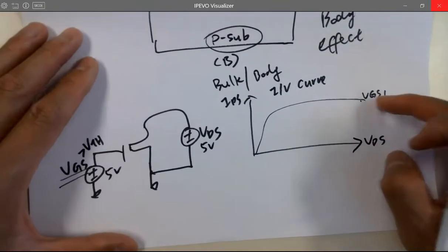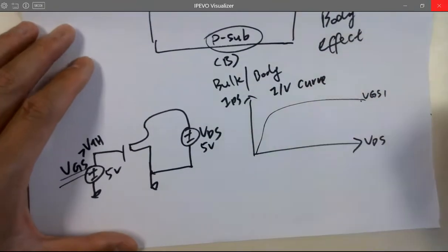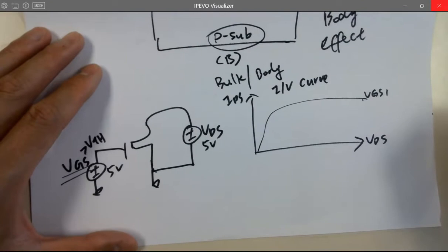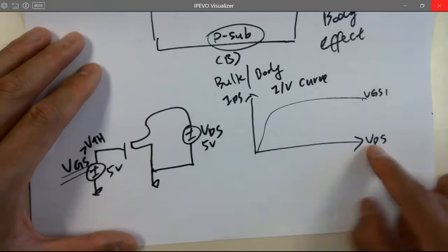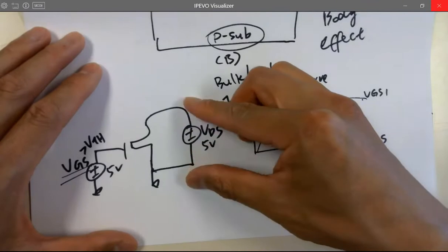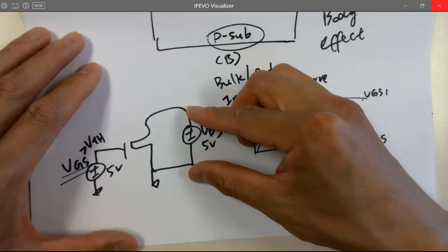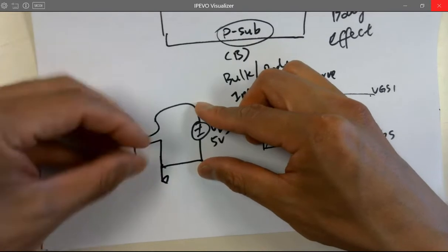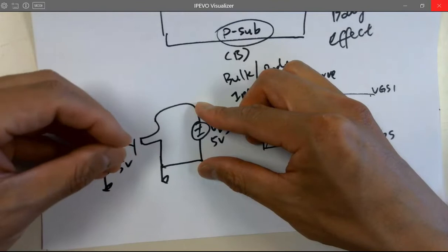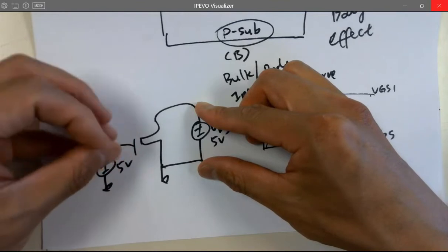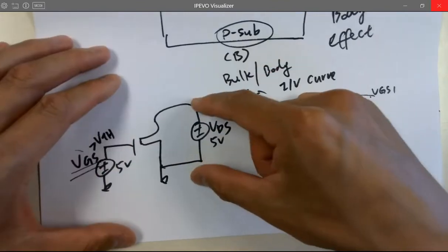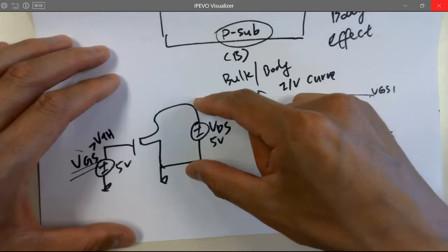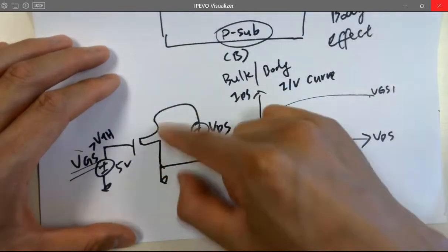So if you decrease VGS, what does the curve look like? So VDS is changing, right? You do a DC sweep for VDS. And how do I understand this one? It's like a faucet, right? It's like a valve of the faucet. You can turn it on to a different level and then give a pressure inside the faucet to pump the water down.